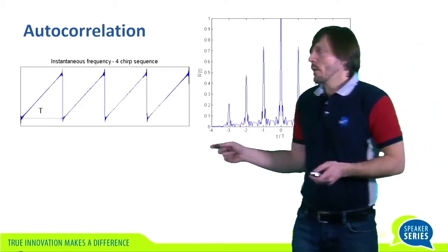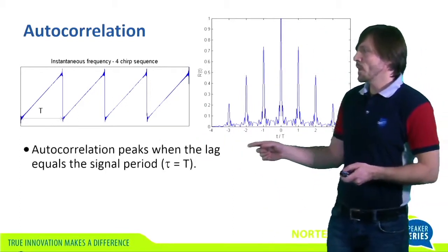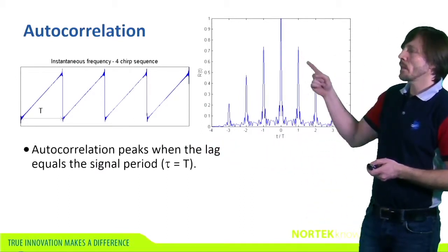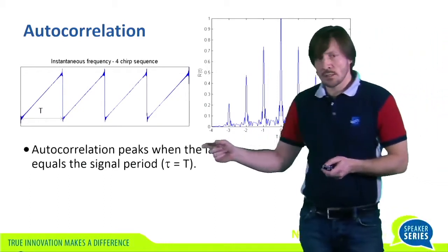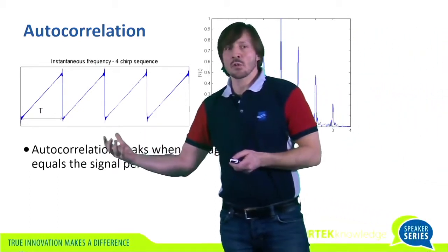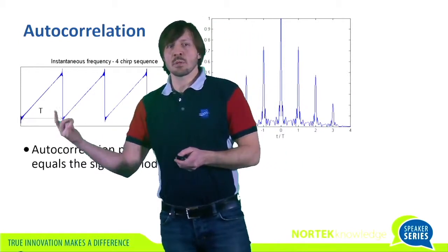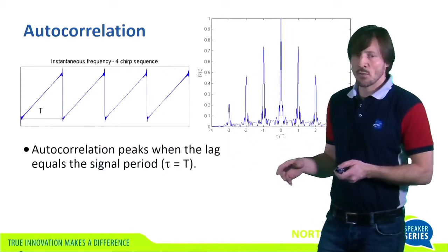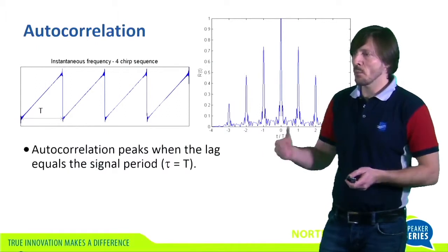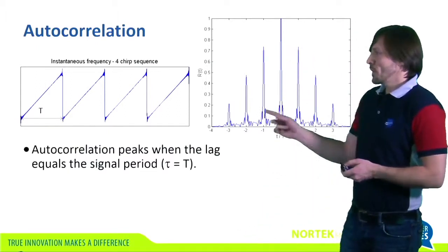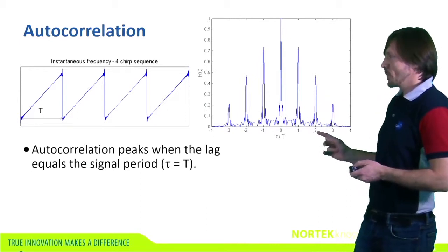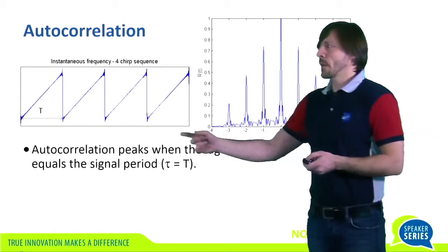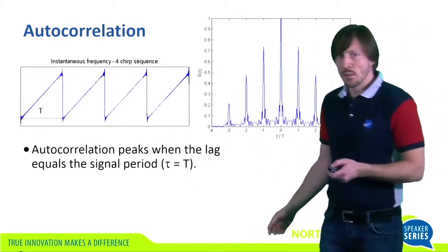And then we find that whenever we move over by 1 period, so here's now one period, we'll find a peak value. That's because we've shifted over so that I'm comparing maybe this chirp to the next chirp. We've shifted the sequence by exactly 1 period, so I expect to find a high correlation, just like those beer sales when I've shifted it by a week. If I shift it again, I find another peak at 2 transmit periods, another peak at 3, and then this 4th one is 0 because now there's no more overlap. That's the end of the signal.